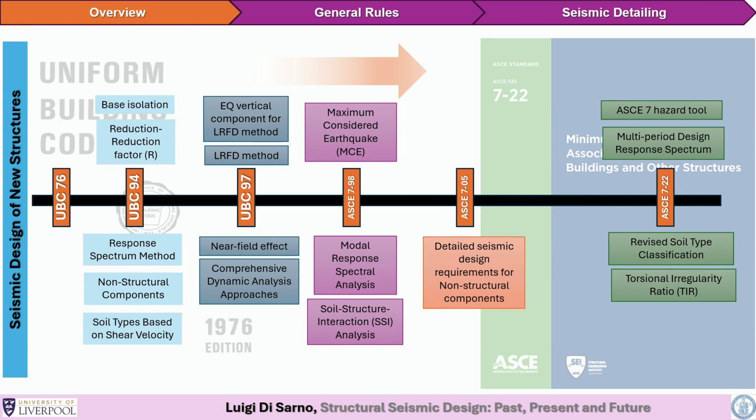seismic areas. And more recently, there has also been a push towards the use of reliability to make the structure safer and safer. And what I mean by safer and safer is that we have been more and more demanding in terms of limiting, for example, interstory drift. We have been more demanding in terms of protecting components that are fundamental for the functionality, particularly of critical infrastructure, like hospitals, like nuclear power plants, or any other type of structure, for example, museums, that are very important. We are working, for example, these days on protection of statues through base isolation, because you want to preserve them